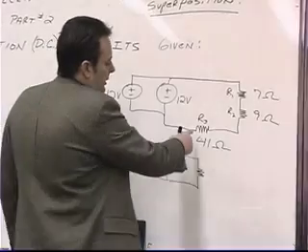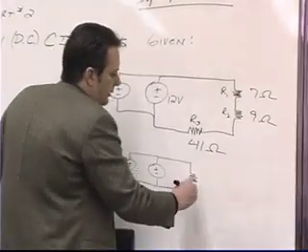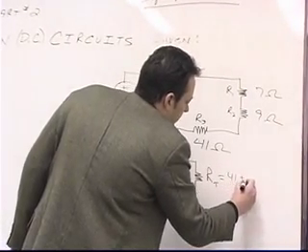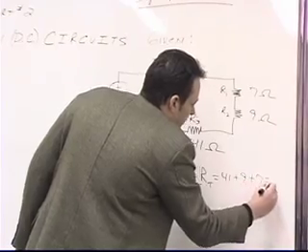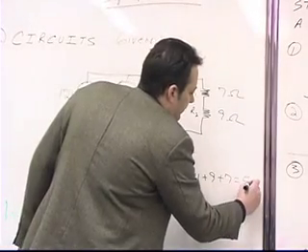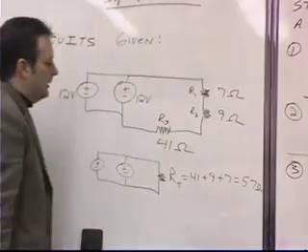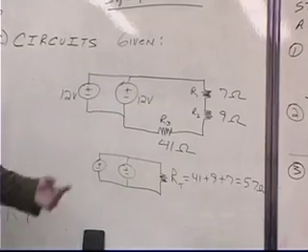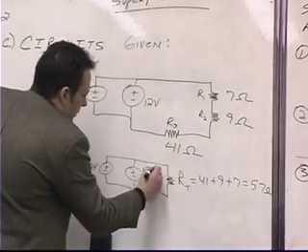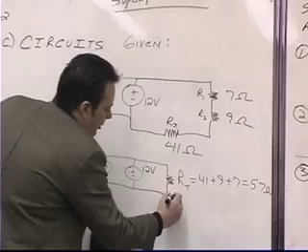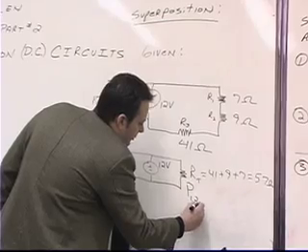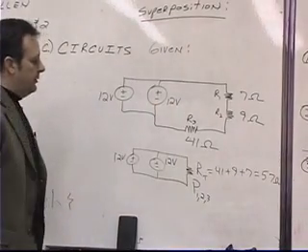And that resistor would be the algebraic sum of these 3. So our total would be equal to 41 plus 9 plus 7. What's that equal to? 57. So that's 57 ohms. Okay? Now, if I wanted to calculate, given that these are still both 12 volts, what the power dissipation was across resistor 1, 2, 3, which is the total resistance,